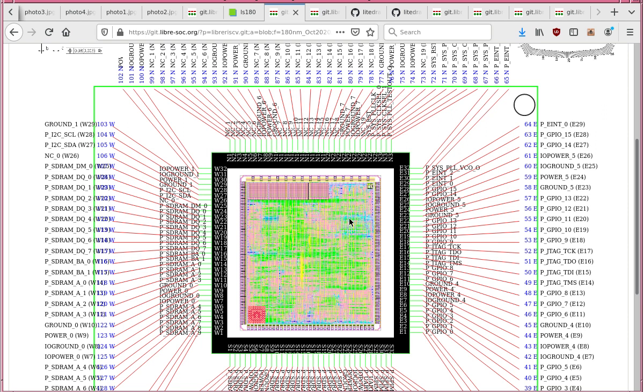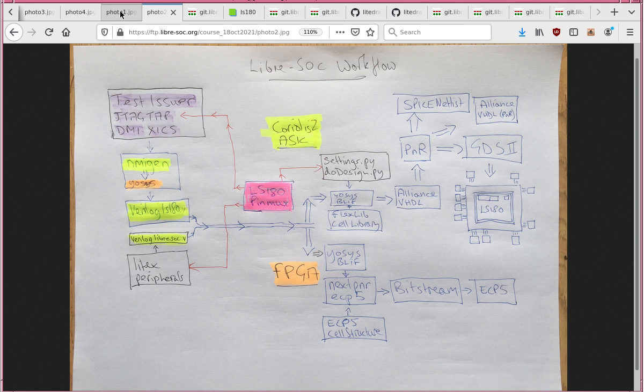And the difference there with an FPGA is that that's a black box, where the tools, nextpnr-ecp5, the place and route tool, don't need to know about that, don't need to route that back out for you, but instead it disappears into a black box resource defined by the manufacturer of the FPGA.